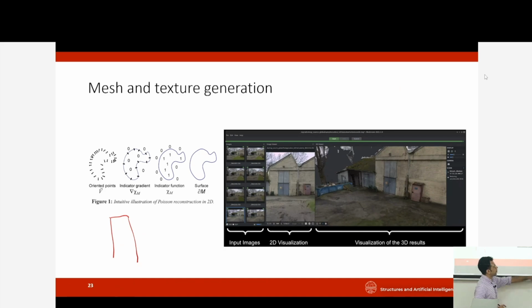So once you do that, you can get textured representations that you can visualize. Now, the source of this texture are the images, but there's some blending that occurs, and there's some averaging, so if your alignment is not perfect, that can cause some distortion in the textures. That's why it's always a good idea to still use the images even after you make the reconstruction, because that way you have the original source of your data.